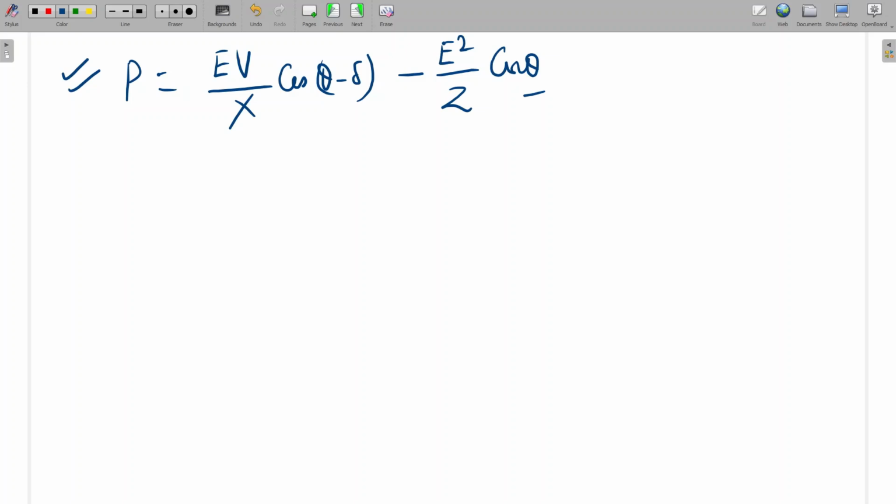In the question it is asking for the static stability limit. What is the static stability limit? That is the maximum power transfer capability of the motor. So what is P max? For P max, we differentiate this equation with respect to delta. Since delta is variable, and load and impedance are constant, meaning theta is constant, the variable here is delta. So dP by d delta should be equal to 0. From here, what will be the differentiation of this cosine?